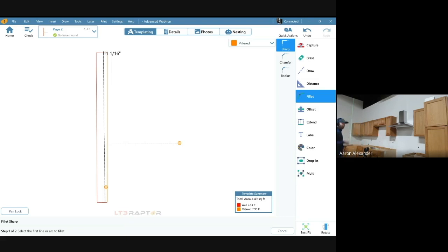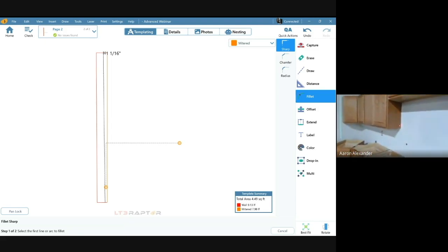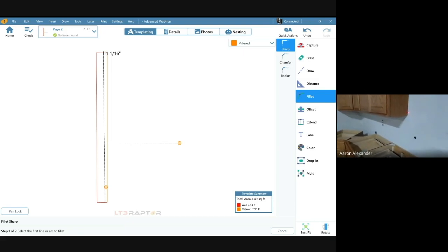So one of the things we got to look out for on these full height backsplash is inside corners. As you guys know, the laser, we're using light to measure distance. So at steep angles, we can get a lot of reflection here, right? So you'll see when I'm going to shoot these points here, obviously I have a ton of reflection off my cabinet right there on any of these shots, right?